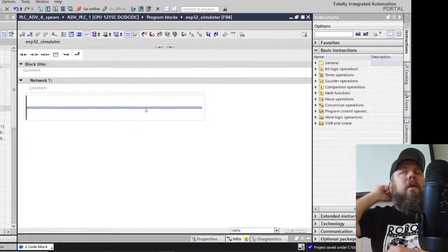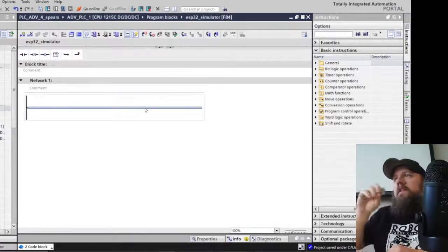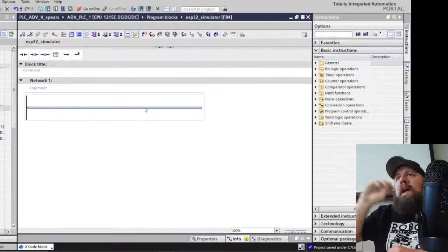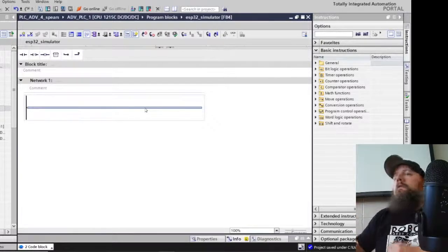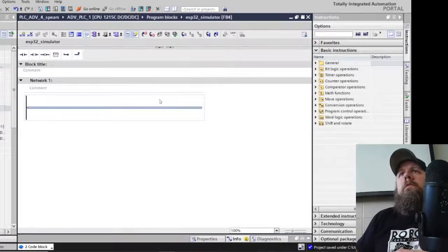All right, so up until this point, if we needed somebody to be able to add something like the analog scaling, we let them choose what output it went to, right? We're not going to do that on some of this. The more I think about it, I'll probably make it so that it won't damage the processor. I could add a little drop down circuit, but we want to make sure that they're just putting out 3.3 volts. Even if I put the protection circuit on there, the output 10 is just wasted as heat.